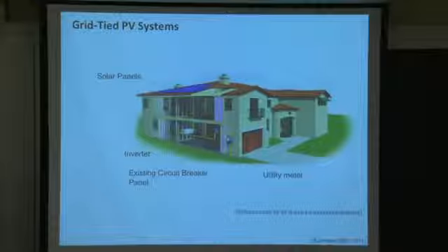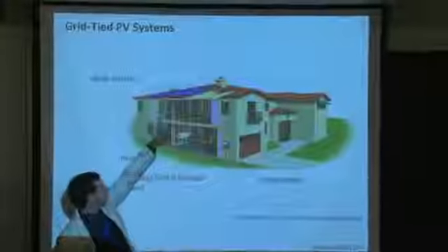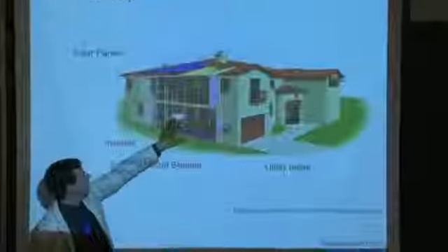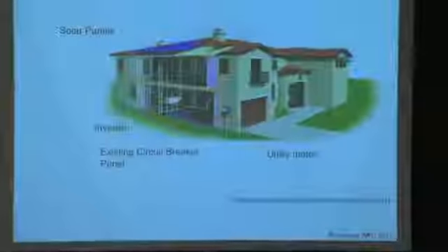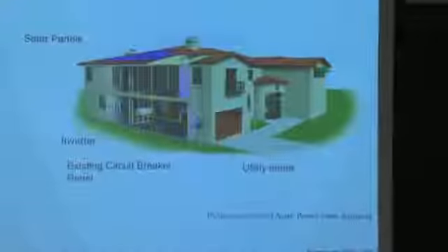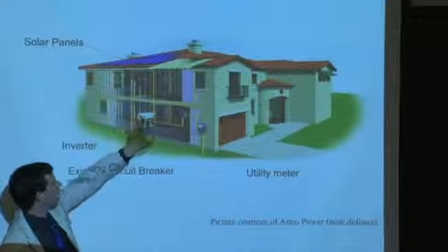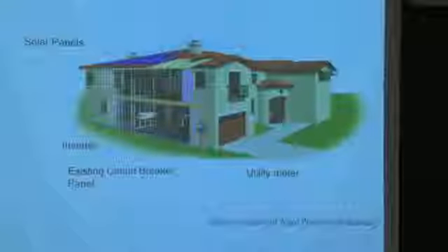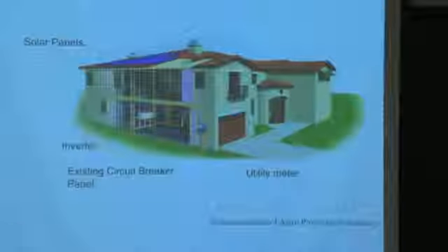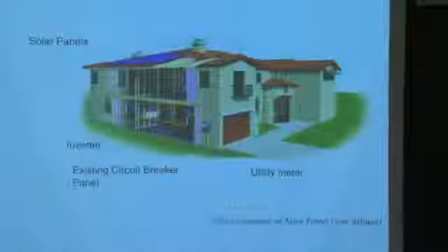Here. So if you're having a grid-tied system, that means that your house or solar array, whatever it is that's producing the electricity, has to be tied to the grid and interface with it. Since the electricity is alternating current, there has to be a device to convert the direct current power into alternating current, and that's called the inverter. We've already touched upon that a few times over today's class. And these objects range in size. For the ones in the house, you could find inverters that are about yay big, that can handle a few kilowatts.